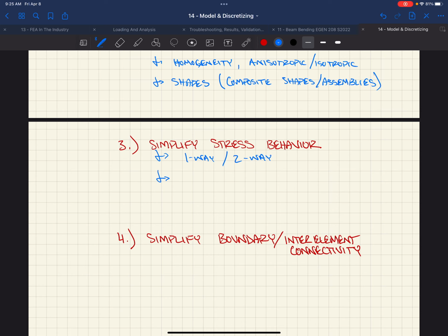So then here, obviously, it makes the most sense, I'm gonna ruin this paper. It makes the most sense that that deck spans this way, load's gonna span this way. But if this was some part of a grander grid system, right, and we had a huge building, right, the chances that you want to tell the fabricator to change the direction of the deck, you might not want to, right, just for the efficiencies of laying this all out and connections of stuff.